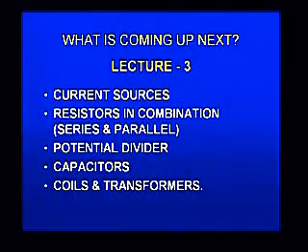Apart from that, there are other components. Again, they all belong to the common category of passive components. Coils and transformers. Coils are basically inductances. They are also used in oscillator circuits and in different applications. Transformers are also very useful for stepping up or stepping down AC voltages, and therefore they are very useful in making power supplies for electronic applications.